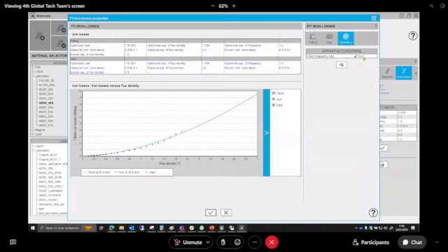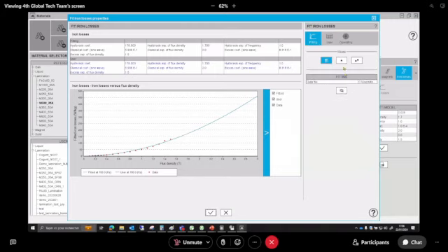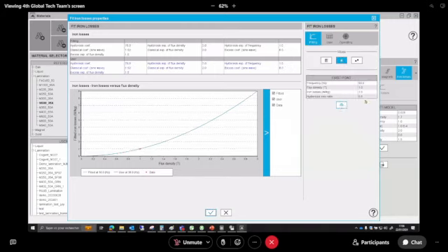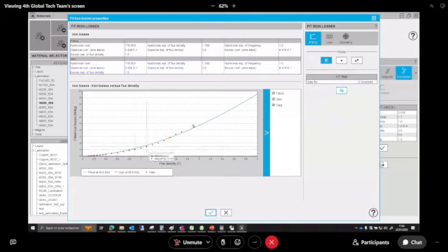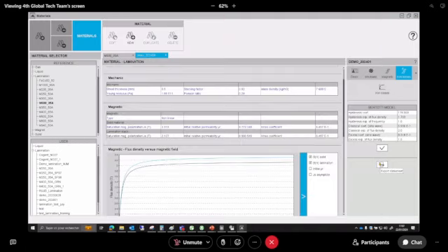Here we do have 50 hertz until 700 hertz. But you can have the measurement for a single point or 2 points. Ideally, it is really to have a measurement for different frequencies, the highest frequency possible, and the highest flux density possible as well. Then the fitting will be done, and you are okay with that.